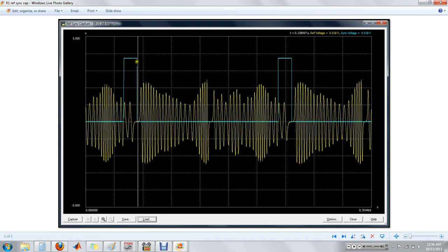So what we could see is this sensor voltage, or this sensor drop, trigger over, and if your index tooth is too close to that, the ECU may jump an index tooth just because of where the sensor voltage read at. So it's important to know where your sensor edge is relative to where other teeth are.